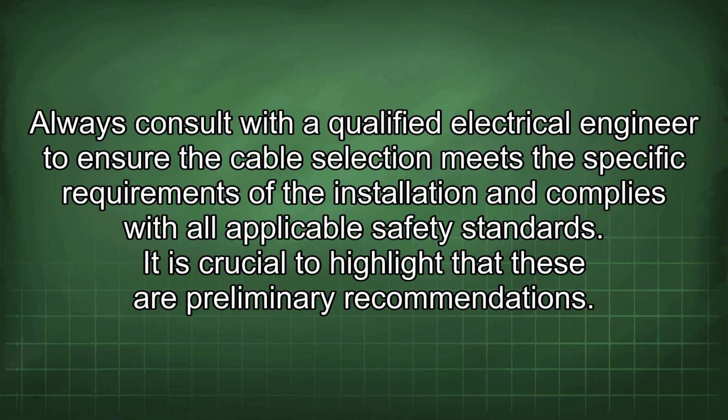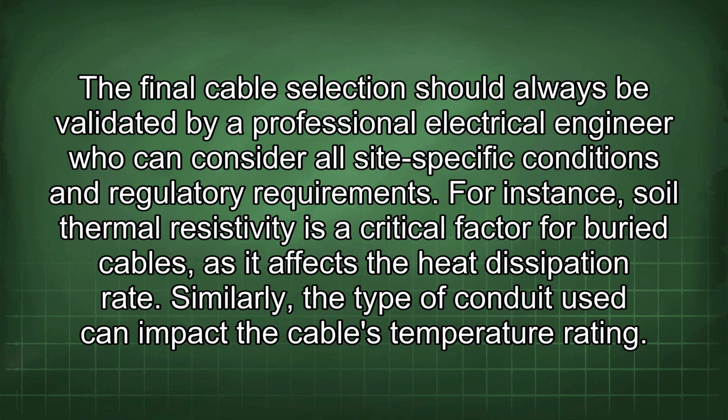standards. It is crucial to highlight that these are preliminary recommendations. The final cable selection should always be validated by a professional electrical engineer who can consider all site-specific conditions and regulatory requirements. For instance, soil thermal resistivity is a critical factor for buried cables as it affects the heat dissipation rate. Similarly, the type of conduit used can impact the cable's temperature rating.